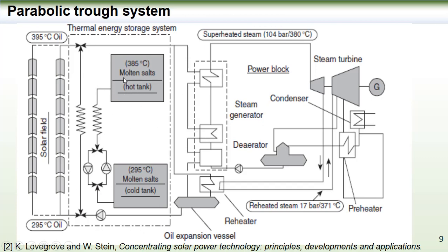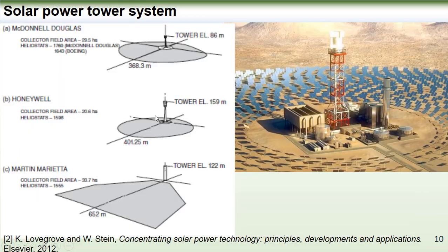Additional thermal storage in the form of two tanks with melted salt is usually installed in this system in order to allow electrical energy generation when the sun is not available for a couple of hours. Some of those systems as well use natural gas to generate steam when sunlight is not available, and therefore facilitate electricity generation for 24 hours. Alongside the thermal storage, the system has the advantage of being dispatchable for a long period of time, in a similar manner to conventional power systems.